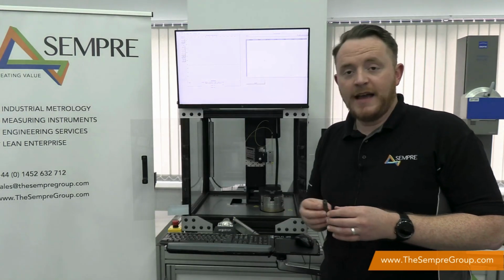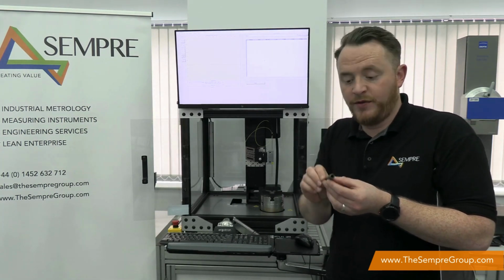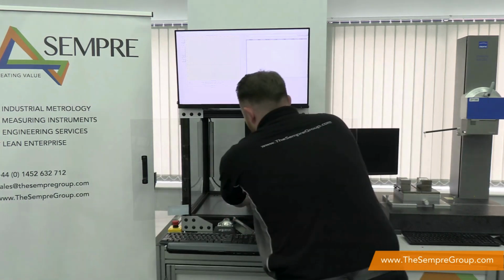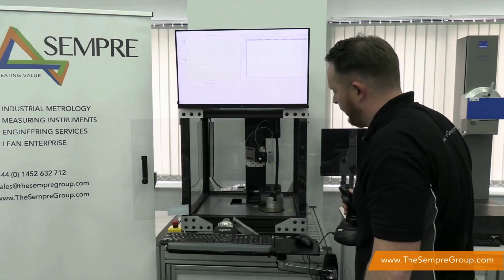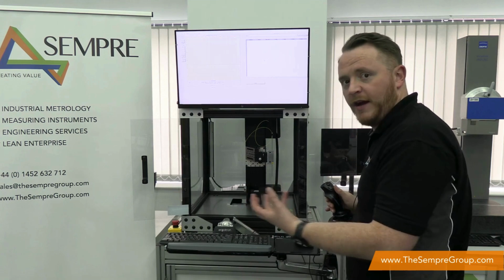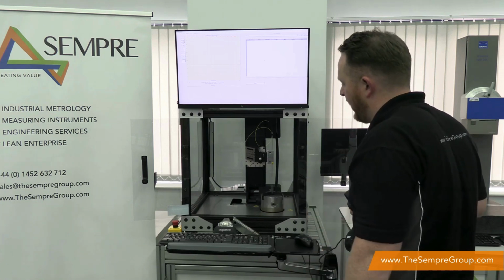So now we're going to take a look at actually creating a measurement routine to be able to measure the internal thread or thread features of this component in my hand. So what I'm going to do is place this component into the machine and just check that the run out of the component in the chuck is okay, which it is. With some more complex features we might have to create a specific fixture to hold the component to make sure that we're running as true as we can to that axis.